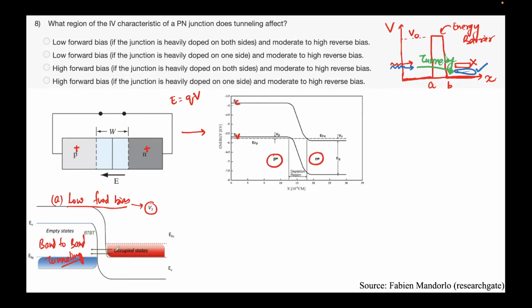And what's happening is that the carrier is being transported, and now the electrons can be collected on the other side, right? So essentially they have recombined over here. The whole principle of that, the circuit is complete. The electrons are being injected on one side, they travel to the other side, and they can now go to the battery, right? This is in forward bias, please remember that. Okay, the circuit is complete, so current will start to flow, and this current is very prominently tunneling.